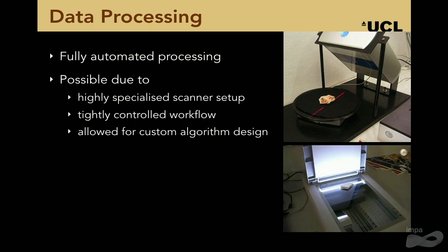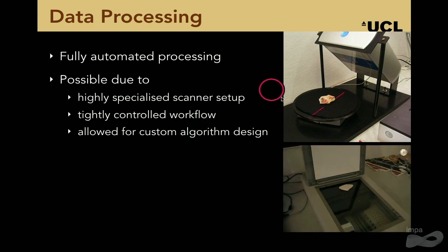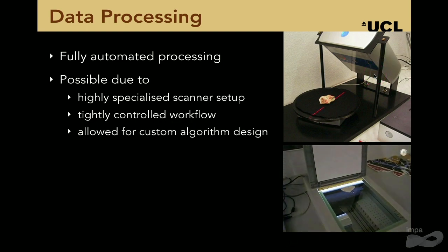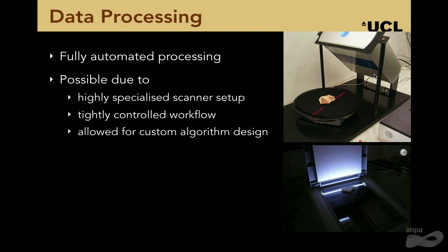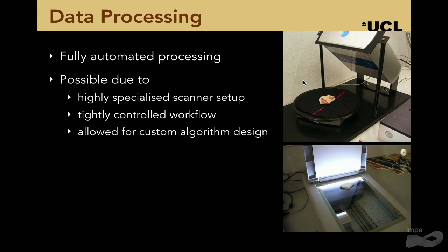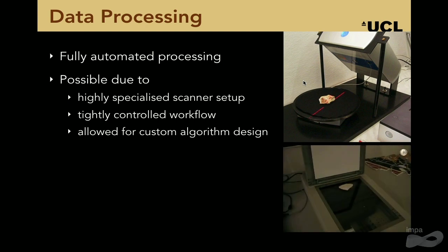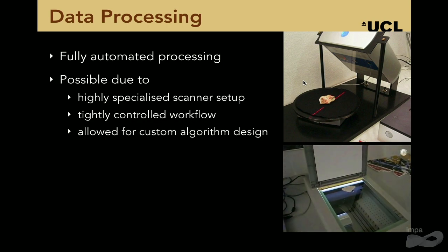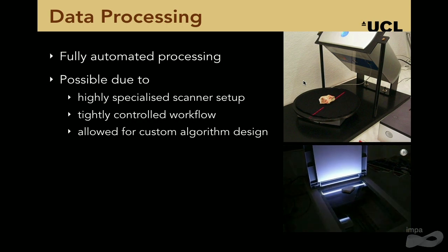And we did additional tricks. We had a bit of an unusual setup of the 3D scanner. We tilted it by 90 degrees. I'll get to that in a second. So it's basically for the specific fragment geometry that allowed us to basically in one go just scan an entire hemisphere, and then we only had to turn it over and scan the other hemisphere, rather than, as you would normally do, scan a cylindrical set of range maps and then having to fill remaining gaps.